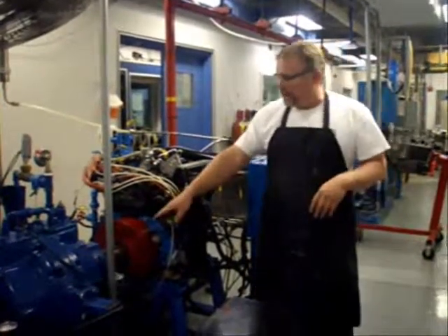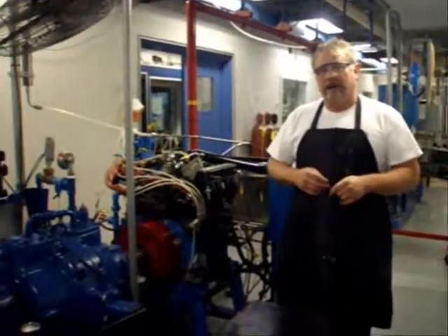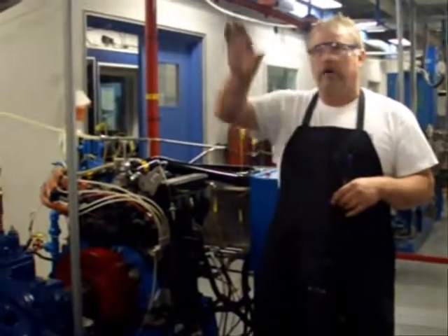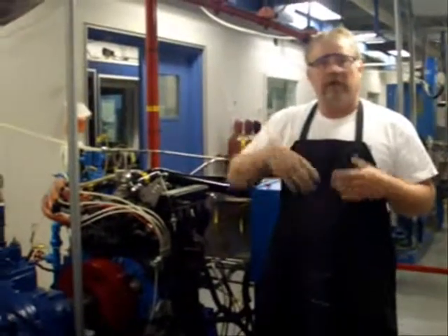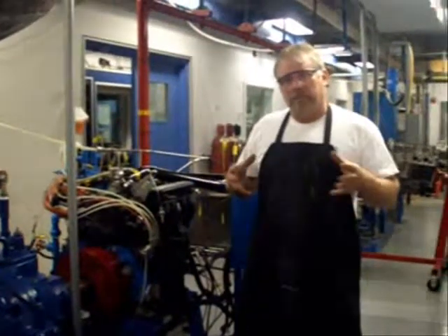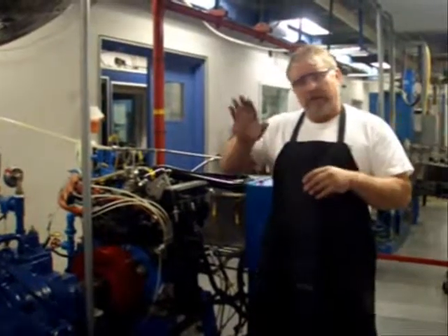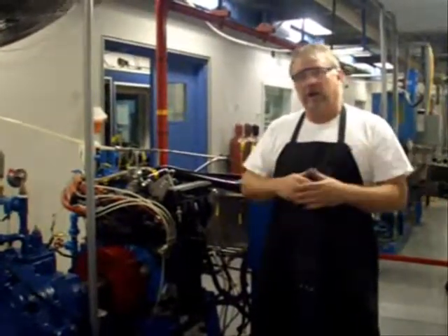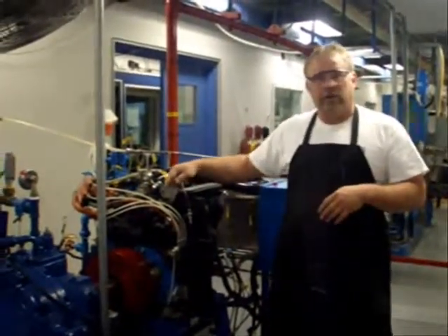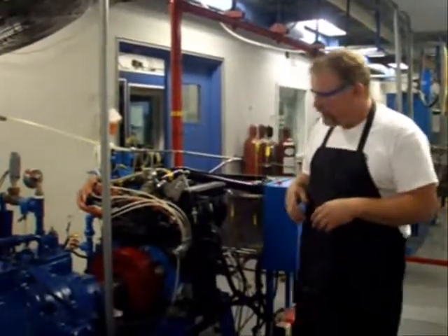The engine itself is coupled to a dynamometer. This blue device is called an eddy current electric dynamometer. We can apply a load to the engine, similar to if you were in a car driving up a hill. The steeper the grade, the more the load, or the more people in the car, the more the load. Using this dynamometer, we can apply a load to the engine and actually get it to make more power. Obviously, when you go up a hill, the RPM goes down, so we can limit the RPM and apply load. We're also able to vary the throttle using a controller out in the hallway, and we'll go over that in a couple of minutes.